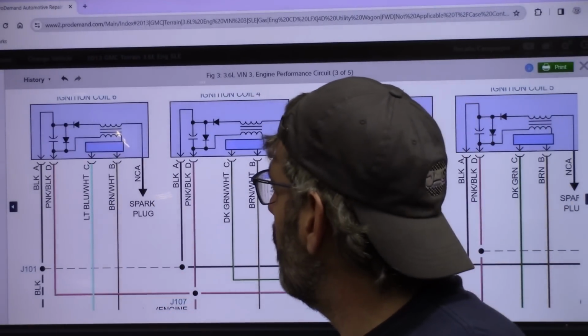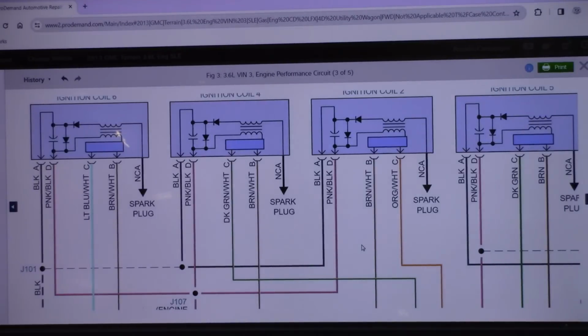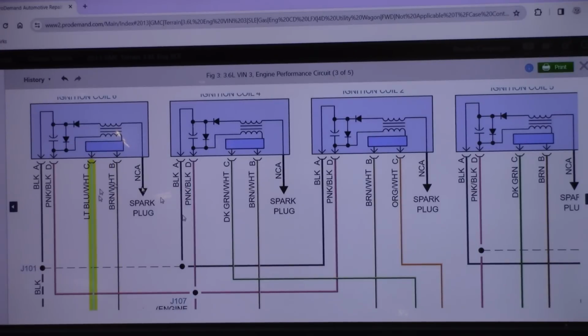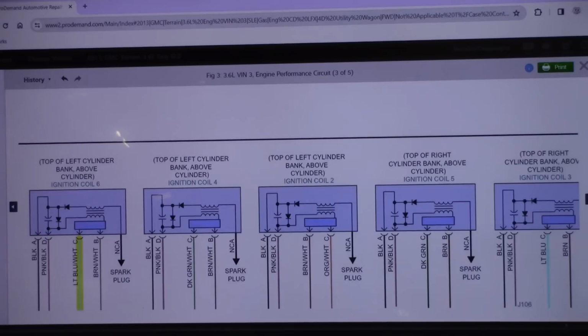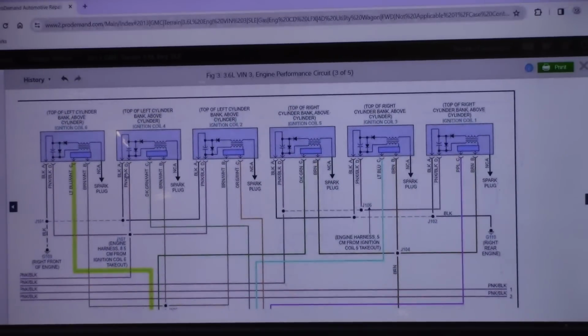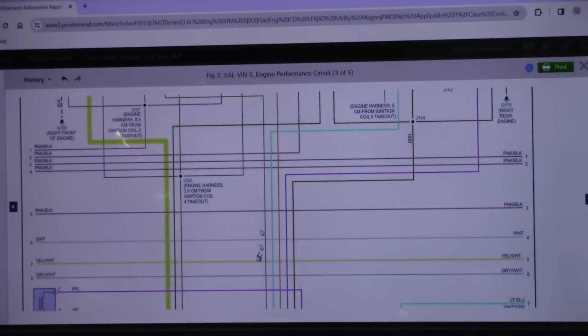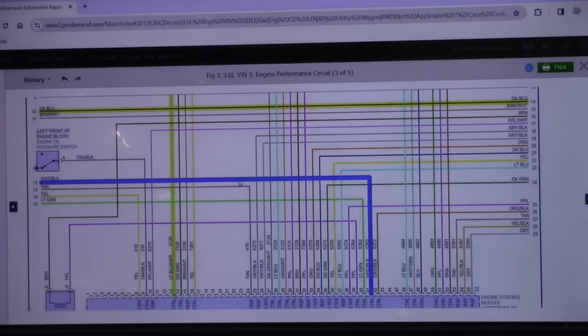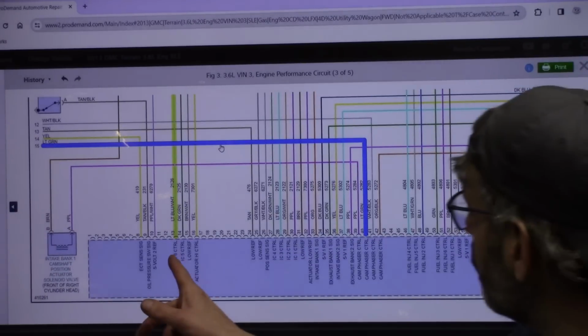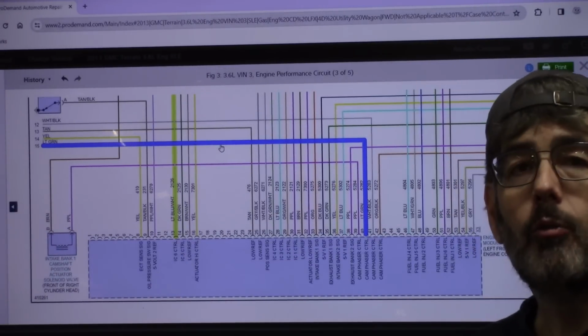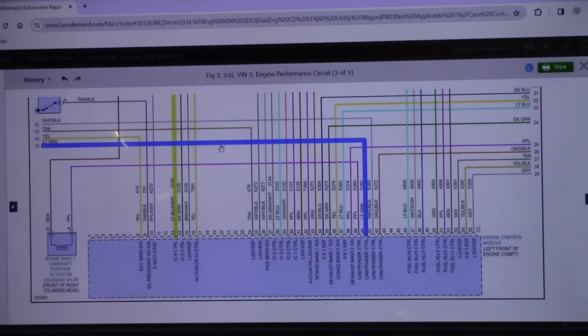But the different colored wire, let's just make sure of that. Let's follow a different colored wire, and let's follow that. And this is going to go into ignition coil 6 control at the PCM. Not sure why these are still highlighted. Oh, it goes right there, and there it is. Injector 6 control, right from the PCM. Okay, that's what we're going to do.